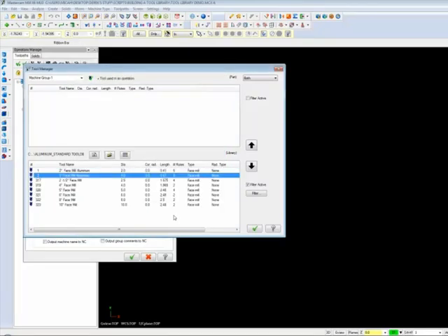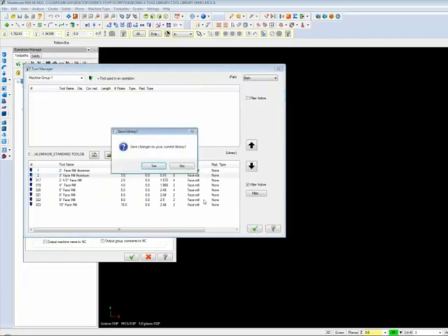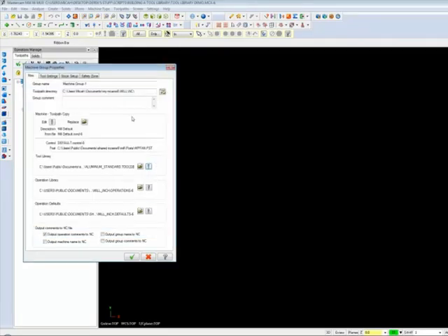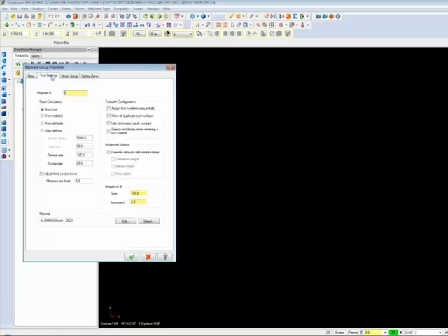Let's see the changes we've made to these tools in action. Click OK to exit the Tool Manager and save the changes to the library. Open the Tool Settings page in the Machine Definition and select Use Tools, Step, Pec, and Coolant. Checking this option tells Mastercam to use the values we just entered into our tool library. Another good option to check is the warn of duplicate tool numbers. Since we'll be responsible to number any tools outside of our permanent tools, this option will ensure we don't assign two tools the same number.